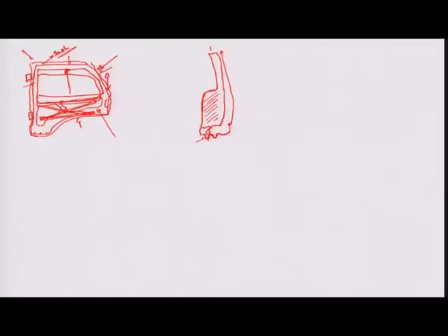Because there are certain holes in the whole periphery of the door which make the fitment of this rubber strip possible, there is always a problem that if some of these holes, because of the natural degradation of the rubber and the rubber coming off, are exposed to splashes, particularly when the automotive is moving on a road, there is a chance of leakage of water from this gap which is created between the rubber strip. So there is a point typically where there is not so much pressure because of some deterioration of the rubber part, okay, and the water may actually go inside the door and create water logging.